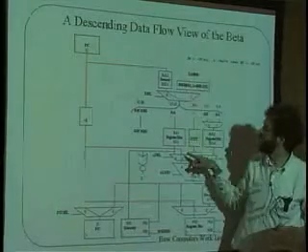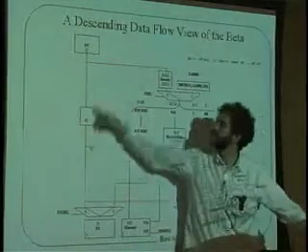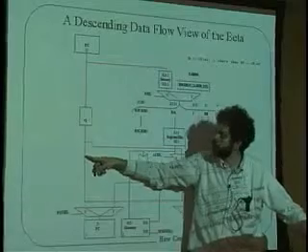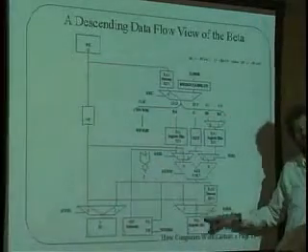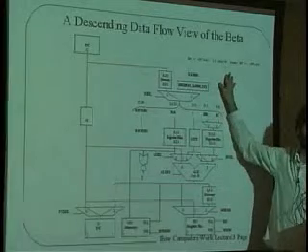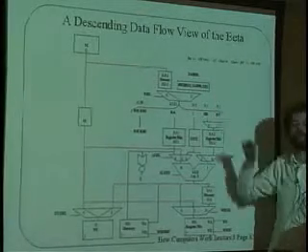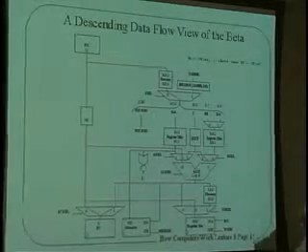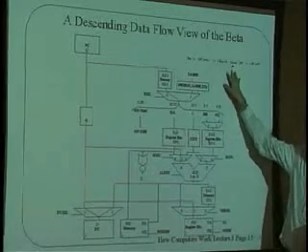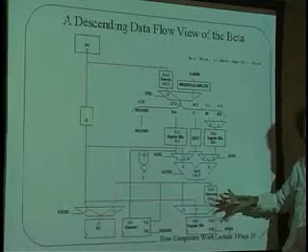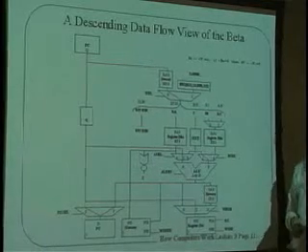But instead, I choose the data having to do with PC plus 1, in other words, what's about to be written into here. So the effect is as if we did them one after the other. The functional description is one of these happening in sequence, but the physical implementation is that they happen at the same time.